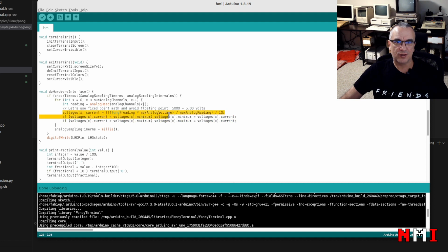It's a little bit more complex to code because it requires more operations and more programming work, but they're all integer, so it's way less expensive in terms of final code than floating point operations, which on an 8-bit microcontroller are all done in software, right? So yeah, that's it.